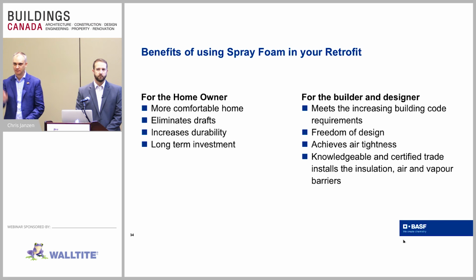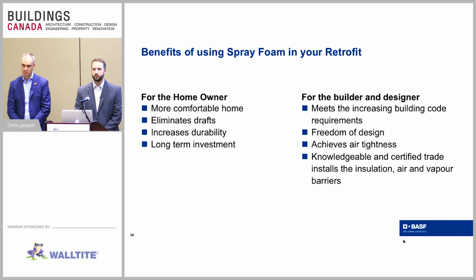I just wanted to reinforce something that Chris and Brian brought up. If you decide to use closed cell spray foam on your projects, they talked about including it on the permit drawings. Include the standard for it: closed cell spray foam insulation and the CAN ULC standard, S705.1. If you include that reference, most of your issues with building officials will go away. If you don't clarify it, they might think you're looking to use open cell foam or some other foam. But if you're specific, most of your building review issues will go away. We've done the training all around that aspect of it being included, so you're just closing the loop.